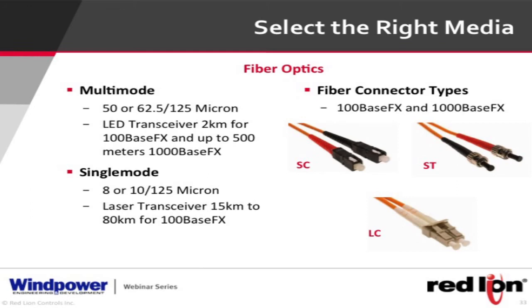The one image that's actually showing here is an SC type connector. Think about it, it snaps in, SC. And ST kind of looks like a BNC type connector, where you push it in, it's spring loaded, and it hugs in. A benefit to that is if there's any vibration at all, it's spring loaded and it's actually twisted on there. So if there's vibration, that'll help you.